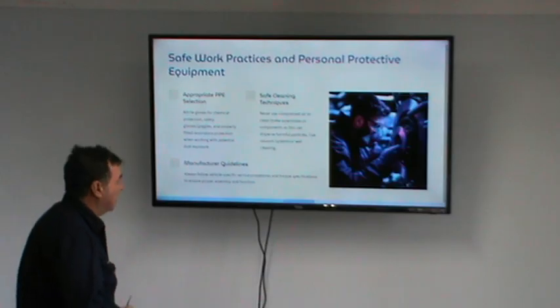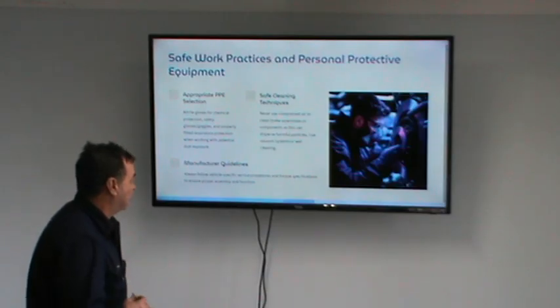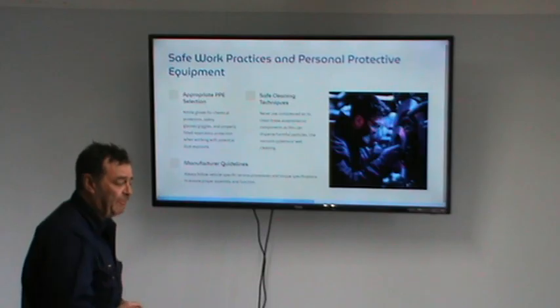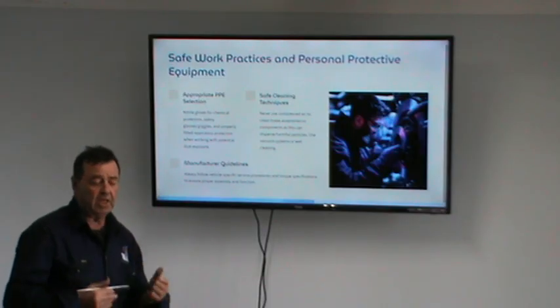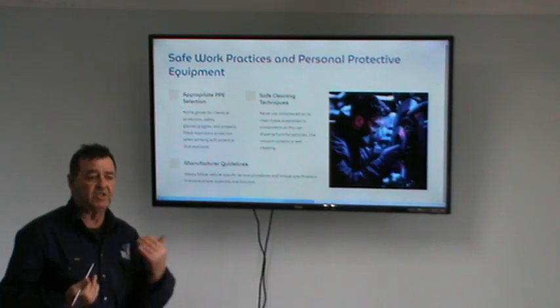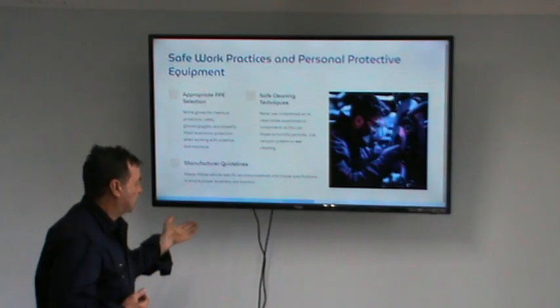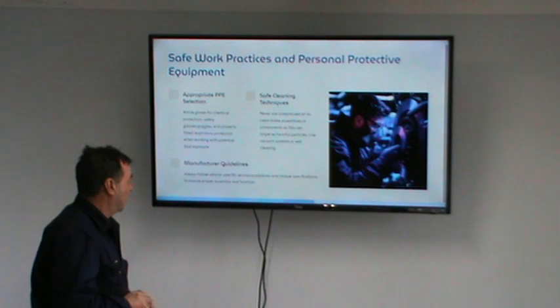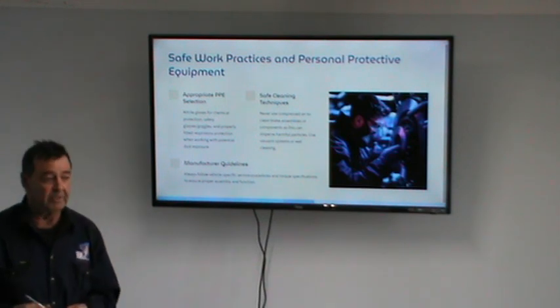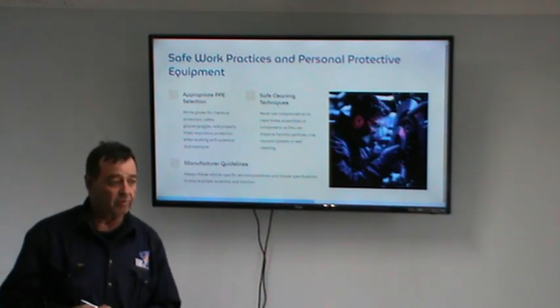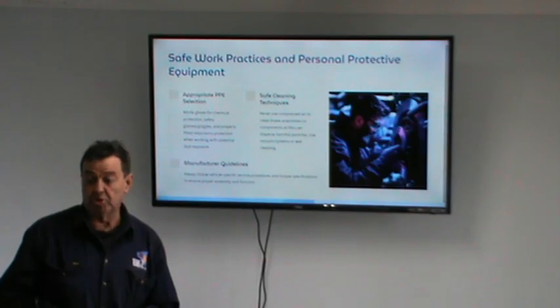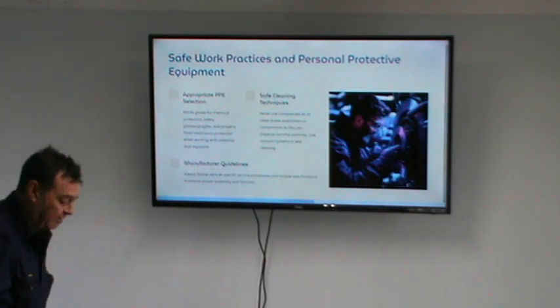Manufacturer's guidelines. Always look to the manufacturer's guidelines because they might have something in their way of doing things that is different. Obviously, we've got to go to it for torque specifications to ensure proper assembly, but we'll do that when we're doing actual inspection on brake systems.